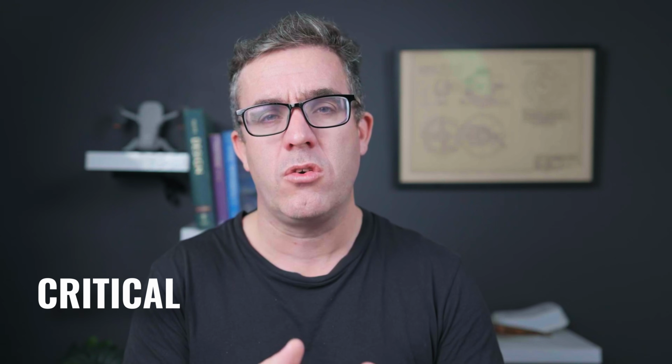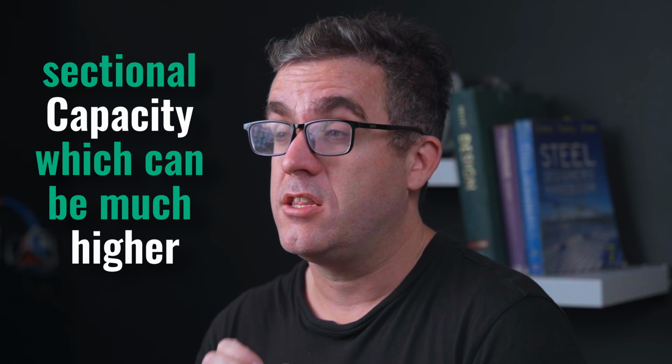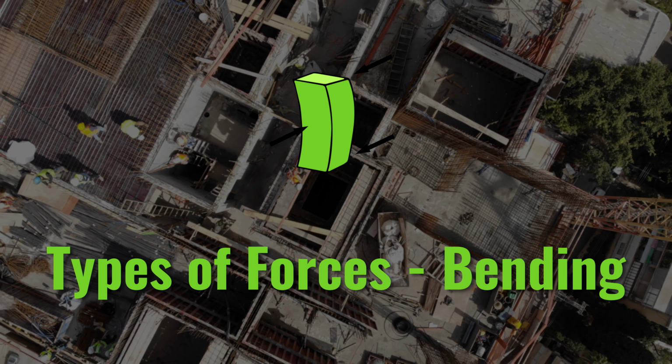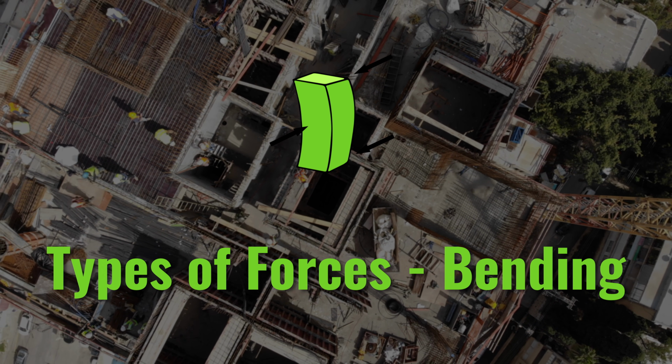So when you're looking at a compression load, you need to fundamentally look at how long is my structure? Has it become slender? And now do I have a critical buckling bending failure? Because if you have a critical buckling bending failure, that is going to be the failure load, not actually the section member. So you see, compression, despite thinking it's a lot easier, it's actually a little bit more complex than your tension actions. Now we'll break down something that's even a little bit simpler, and this is bending forces.